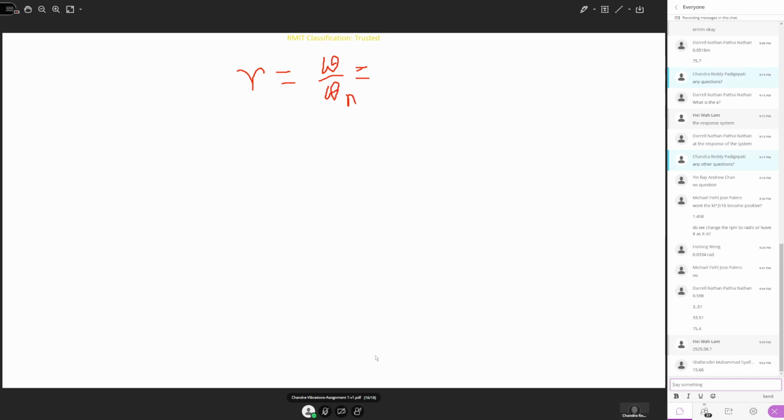Okay, so we know the logarithmic decrement delta. You got it as 0.598. So this one we can equate, considering the damping constant, because this is a reciprocating mass. We consider the damping ratio is low, so we can equate this with 2 pi eta.